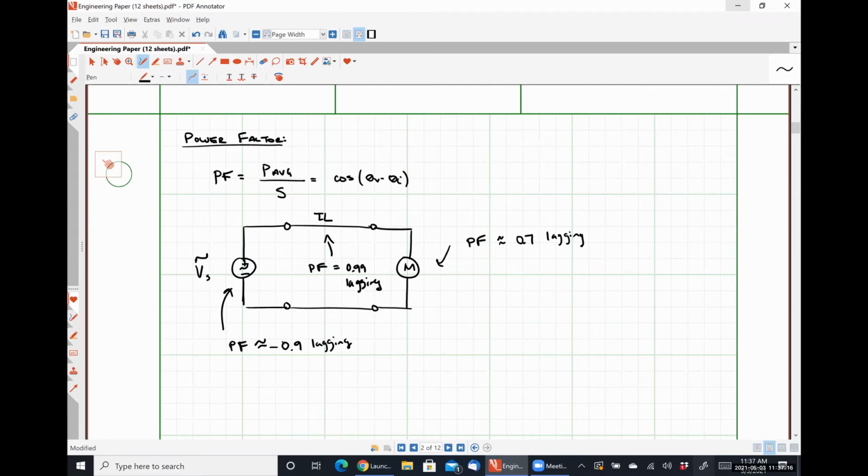So what they employ is a practice called power factor correction, which involves putting a capacitor in parallel with their distribution system in order to make the power factor of their whole system look good. The power factor is higher than the minimum threshold, meaning they don't get those fines. So the reason increasing your power factor makes the electric company happy is that they don't have to pay more money to supply it to you. It's really that simple.